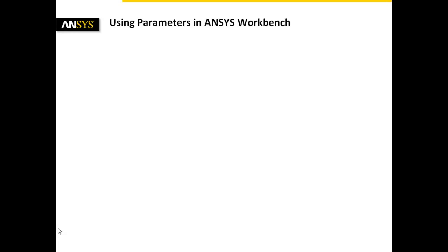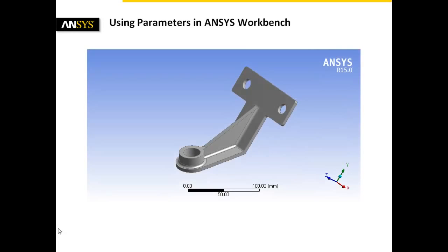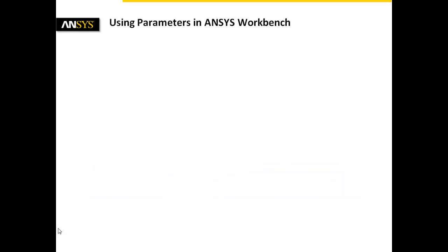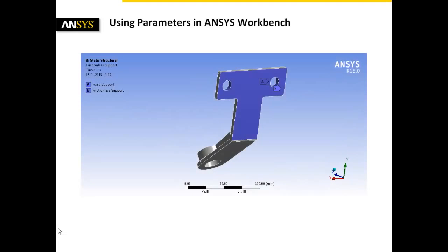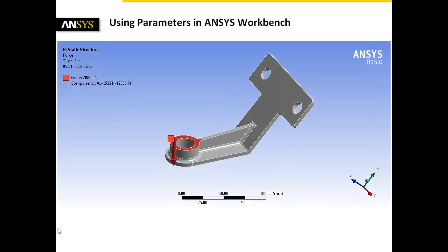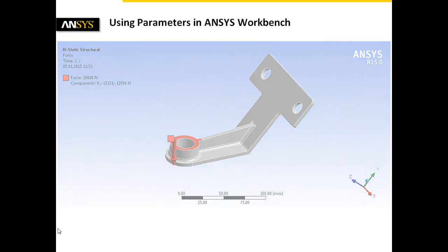The following example focuses on a flange bracket. It is based on a welded structure which enables the use of different sheet metal thicknesses. When installed, it will be mounted with two walls supported by a neighboring structure. Therefore, a fixed support and a frictionless support are defined. The load is represented by a force directed perpendicularly to the cylindrical lug.